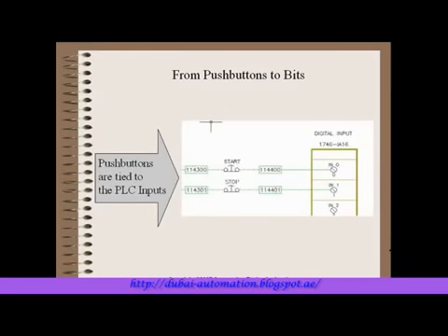So what's the difference between the PLC and the regular hardwired option? Well, with hardwired, you saw we take our push buttons directly to a relay, and it acts directly upon that relay. With the PLC, we have our start button, and it comes into an input card. It's wired directly into cards that interface directly to the processor through a rack or some other means.